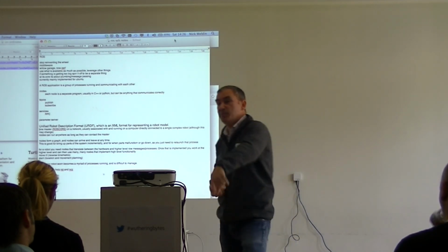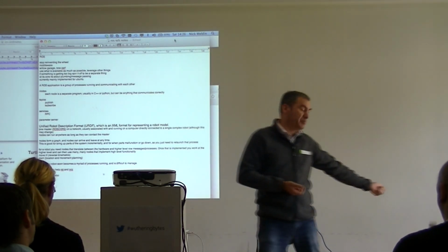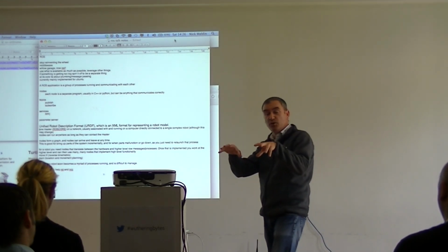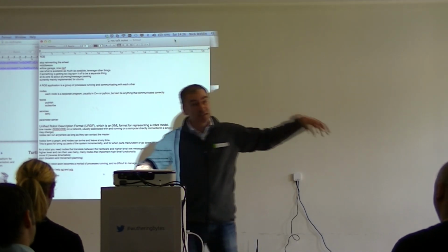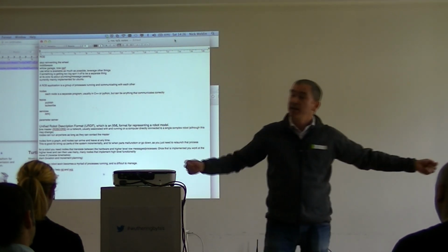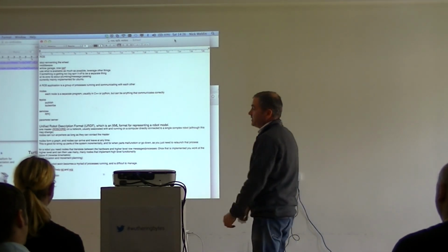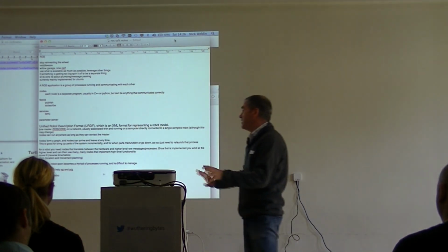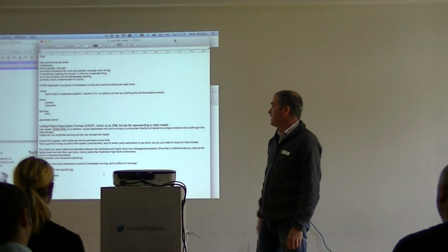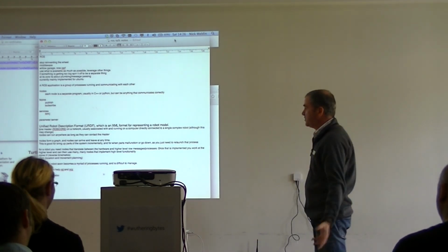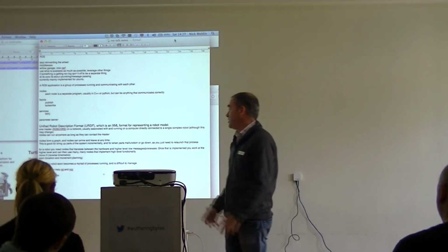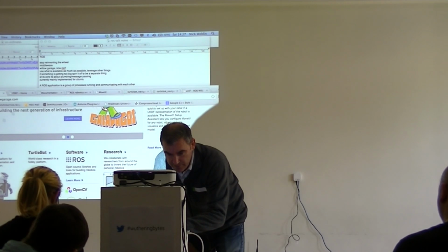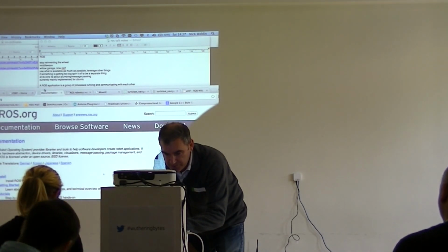You want to be sending information back, calculating a path, sending the path back to the robot, so the robot then goes round it. So you can be developing stuff on one computer, you just need to move the nodes onto another computer and launch them on there, and they'll find the core and hook up and take care of everything else themselves. So the nodes form a graph, and they can arrive and leave at any time. And a complex robot soon becomes a huge myriad of processes running, and it's quite difficult to manage. But it does loads of really, really good stuff.